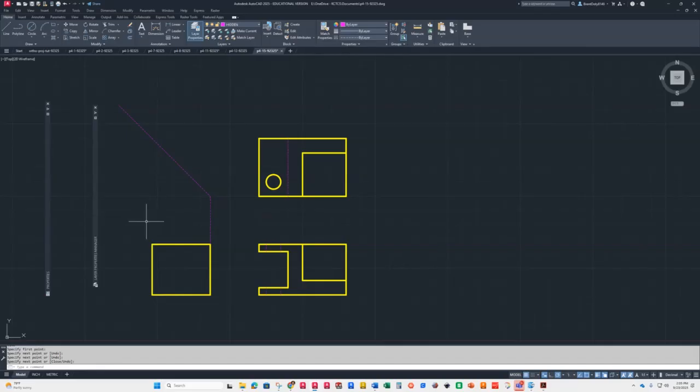All right. So on this end, the reason I wanted to draw it is because these two surfaces here will be solid. So I can change layers again. Go to object line, draw me a line, draw it over, draw it over, and then we'll trim it up.